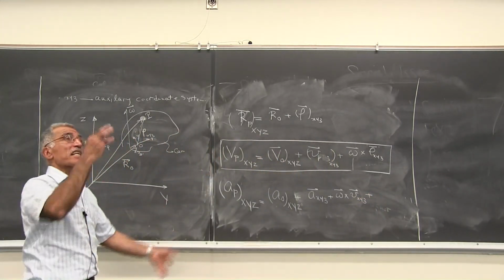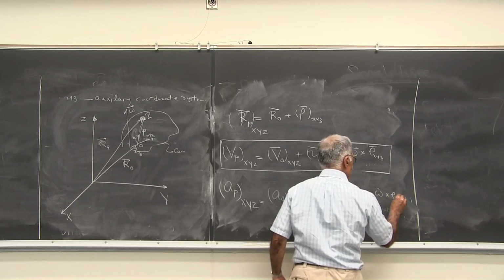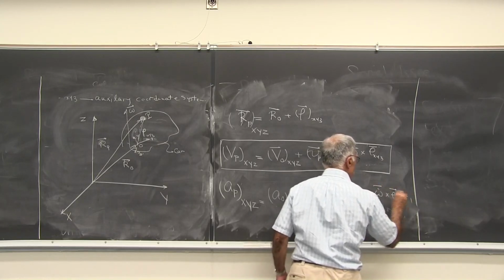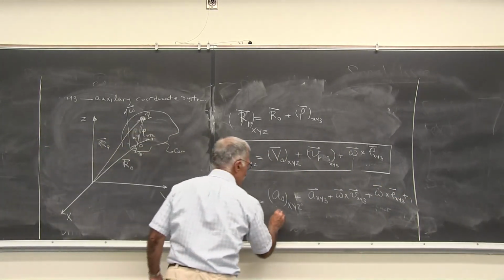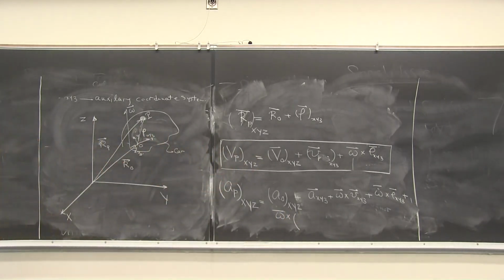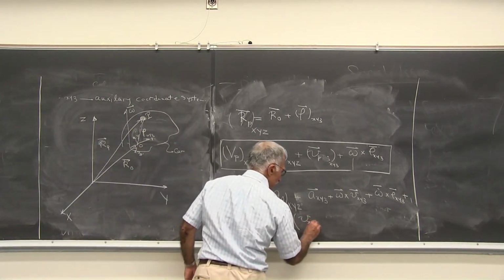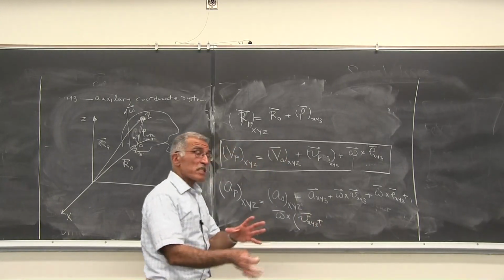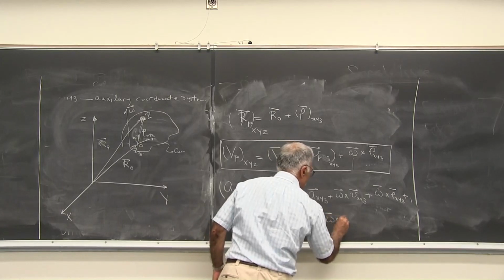Now, if your car has angular acceleration, then you have omega dot. So you have omega dot times rho xyz, plus. Now you have to say omega times the derivative of that expression. What's the derivative of rho dot? We just mentioned that. It is a Vxyz plus, but because rho itself is being twisted, it has an additional thing, that's omega times rho xyz.